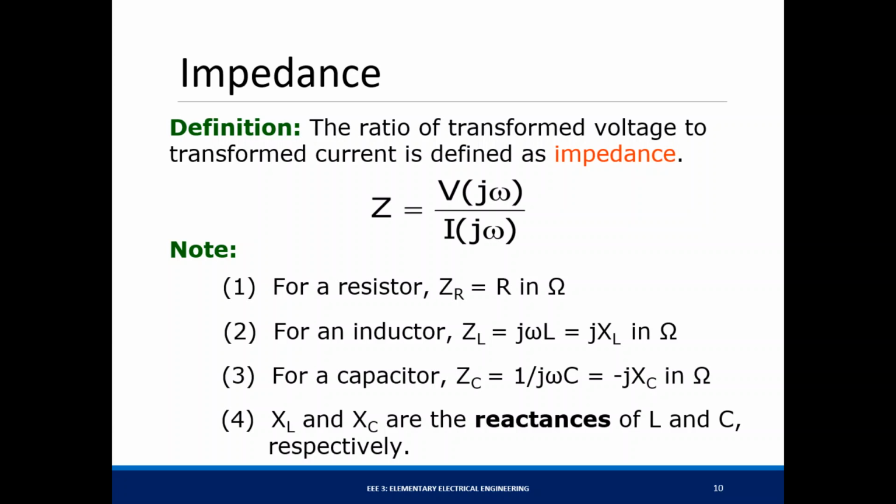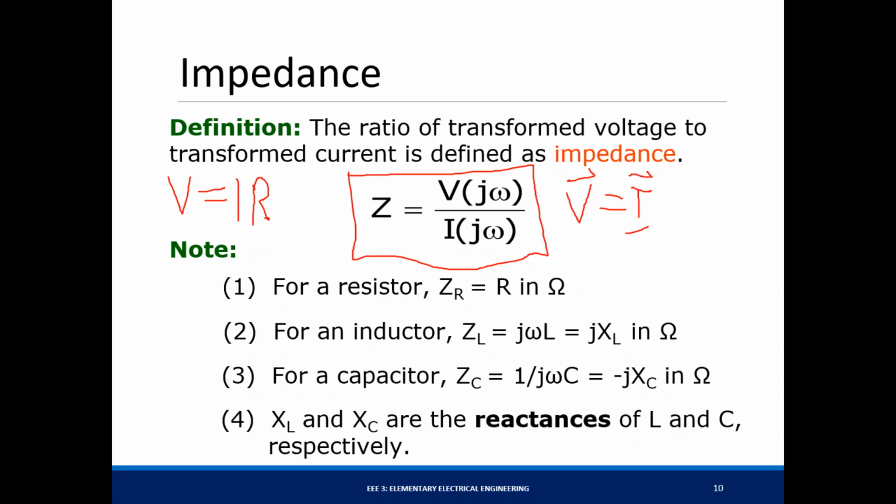If we have real numbers and we can extend them into complex numbers, we can do the same to the resistance of some device. We can extend it to what we call an impedance, where your number has a real part and an imaginary part. So the impedance is kind of like the resistance, but in this case, it's complex, and it's defined by Ohm's law right here. If Ohm's law in the DC case is V equals I times the resistance R, Ohm's law in our phasor form is V equals your current times Z.